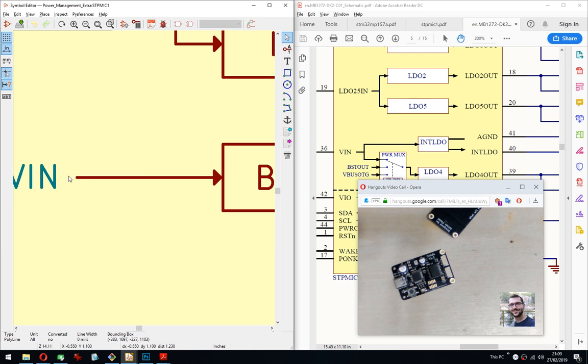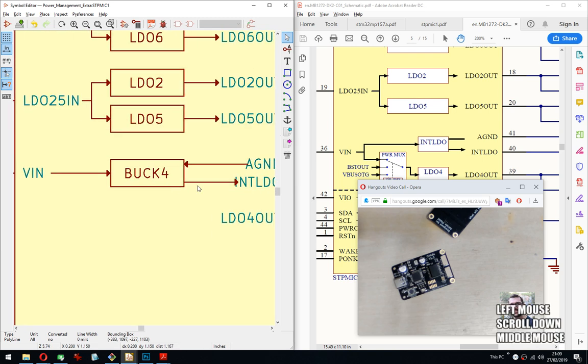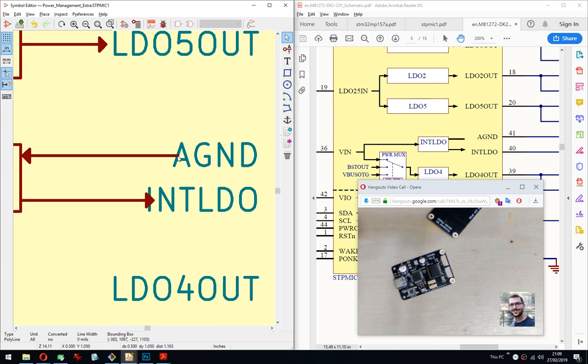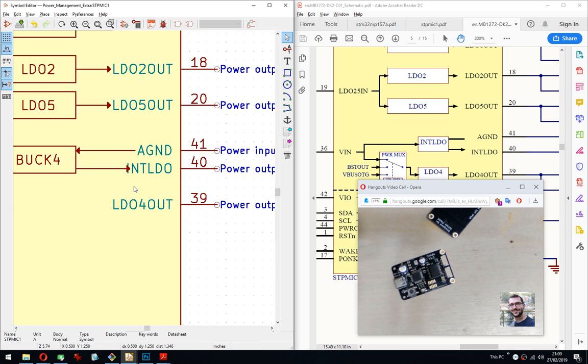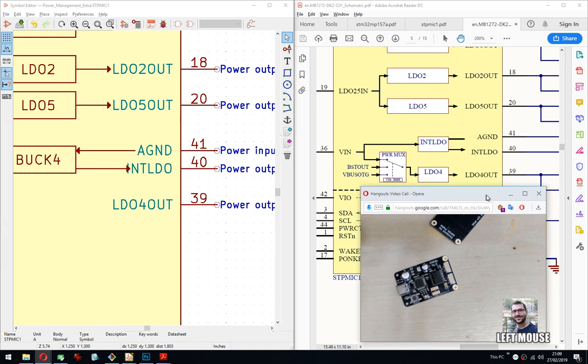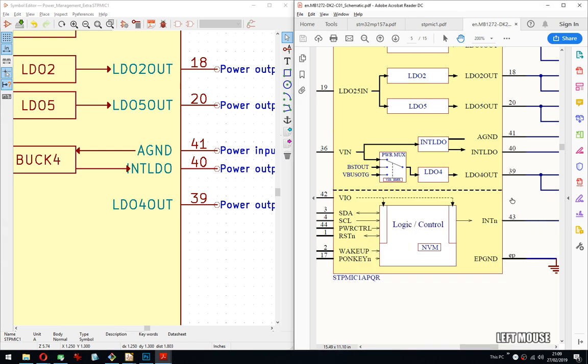Instead of 10 mils, which are most of the traces on this board, I had 5 mil traces. That's the maximum that my board house can do. I probably would have had to scrap half the boards because I would have ripped off the traces from trying to solder it. Yeah, it would have been too much heat.